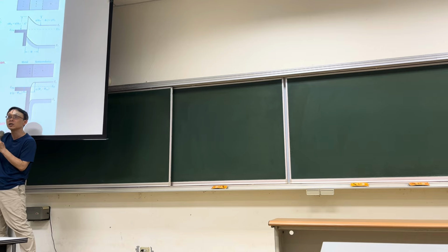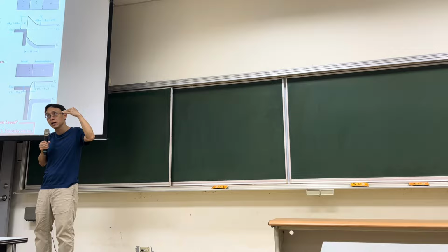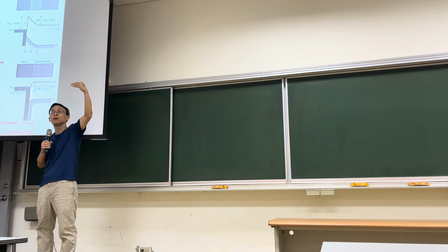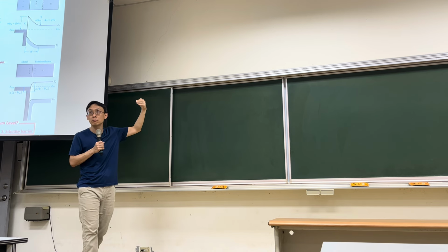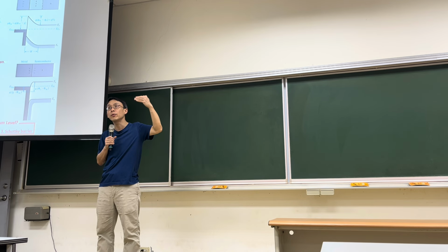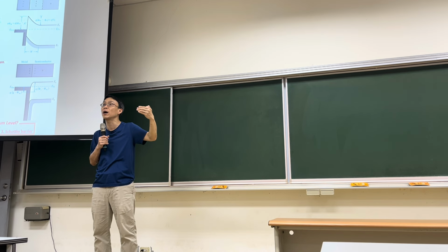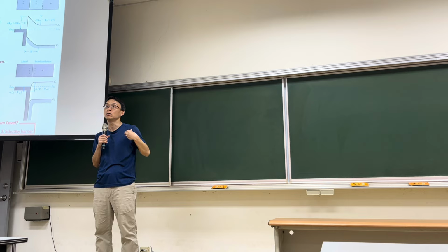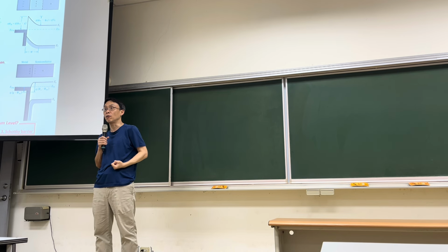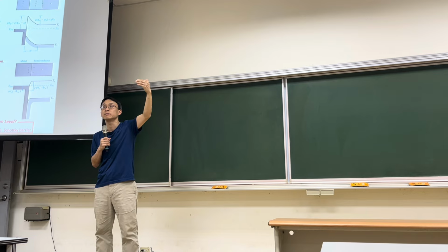You need to know what's the definition of work function, right? Which is the energy difference between the Fermi level to the vacuum level. You need to know what we mean by vacuum level, right? That's the spatial reference energy level in semiconductor band diagram. That's the minimum energy level for the electron to be free from any material, right? It's like you shoot a rocket from the Earth to the outer space, free from the gravity of the Earth, right?